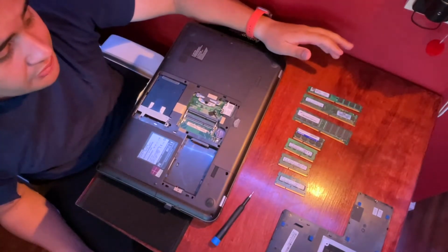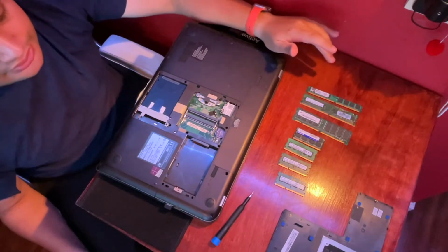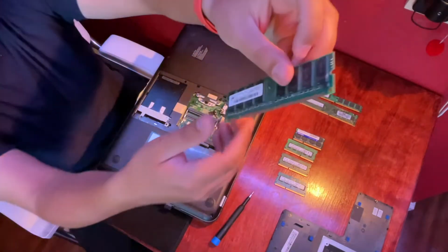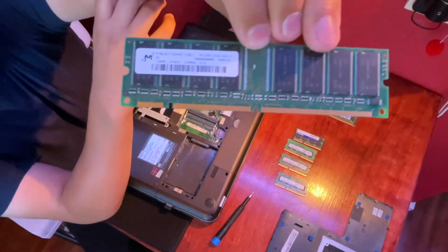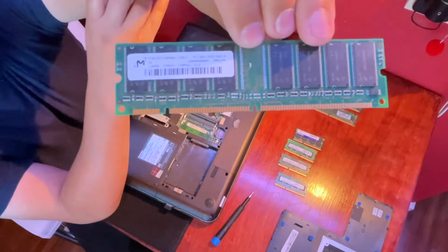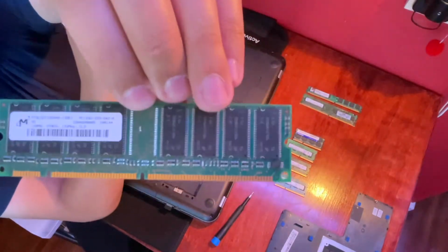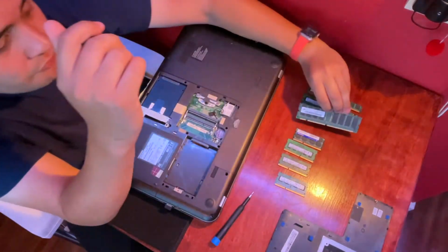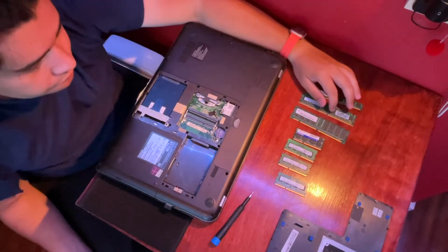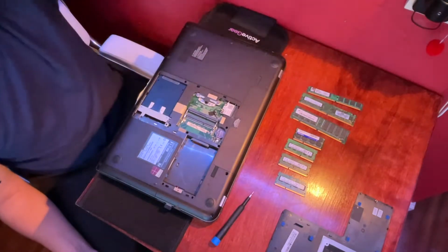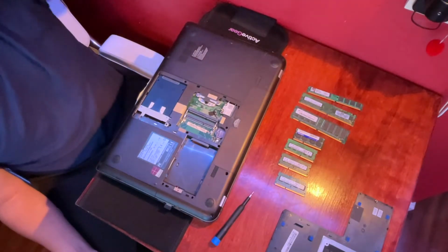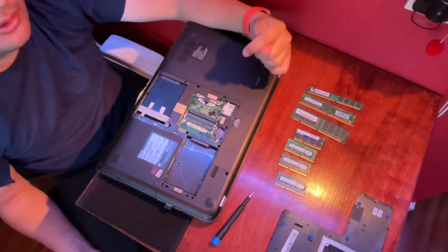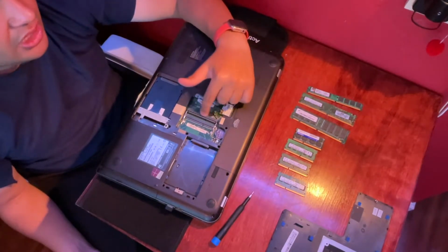And this is what we call regular DDR. There's another one, as you can see here, where there's a missing chip. If that one was populated, it would be what we call ECC, or error correcting and checking. Normally you see those in servers, and an ECC version will not fit in a regular slot, but a regular one will fit in an ECC slot.